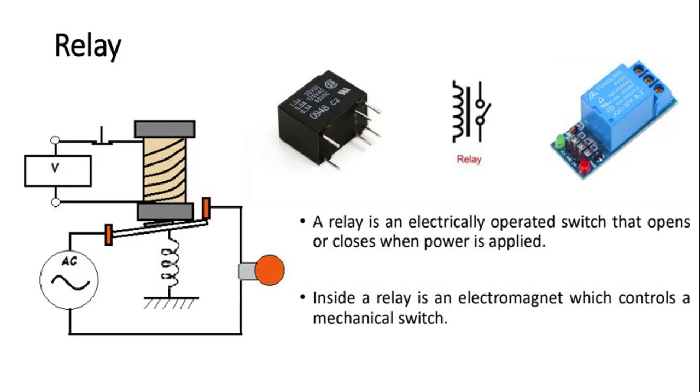So as we know, this motor or these particular signals will get controlled, and we require a relay in between that particular signal and the motor. We cannot directly connect that motor to any supply, or directly to the processor itself. So we require a driver circuit, or sometimes, to turn on and off a light or bulb, we require a relay.